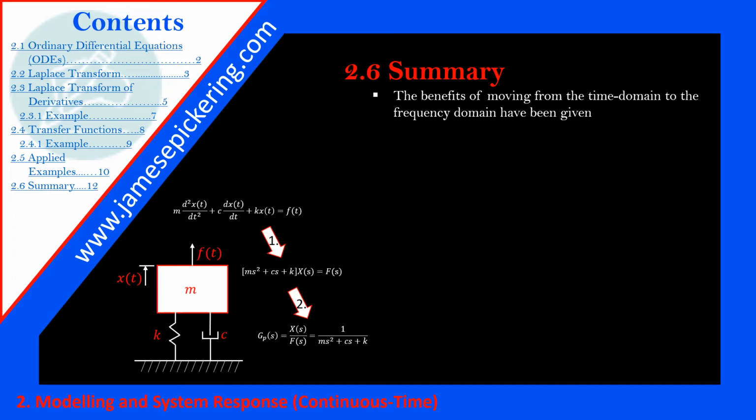So in summary, the benefits of moving from the time domain, so ordered differential equations, to the frequency domain, or the complex frequency domain of Laplace, have been given. You've been able to see that we can go from this ordered differential equation, undertake the Laplace transformation you saw in video 2 of 4, and then algebraically manipulate the equation, because when you convert into Laplace, you can treat the input, in this case F(s) force, the output displacement and the model here as three separate entities. So what Laplace enables you to do is to algebraically manipulate the equation.